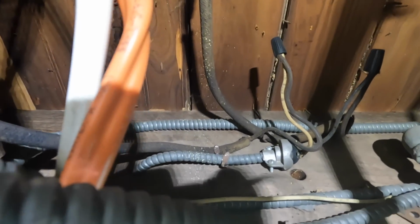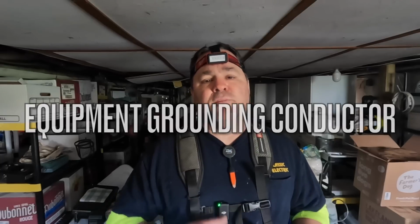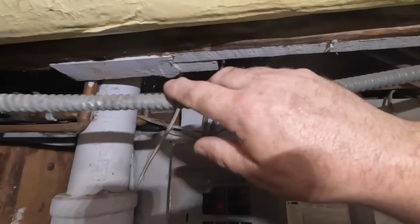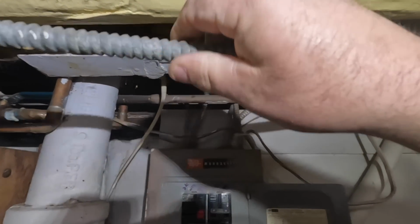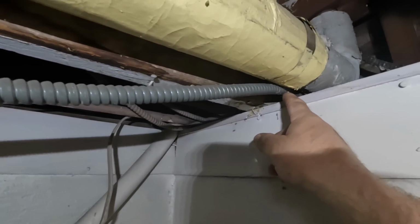And the improvement over knob and tube with the BX cable was that the BX cable actually had what we know now as the equipment grounding conductor. So the actual sheathing that goes around the cables, that's the BX portion, actually acts as the equipment grounding conductor to safely return fault current back to the source to facilitate the circuit breaker and clear the fault.